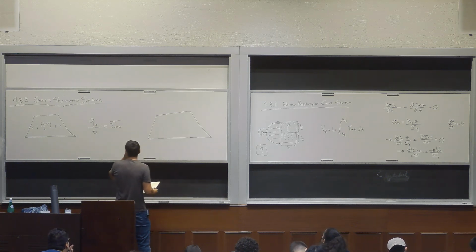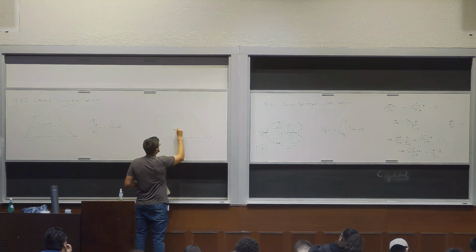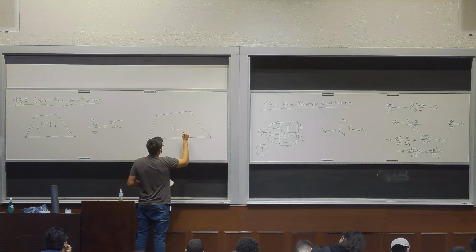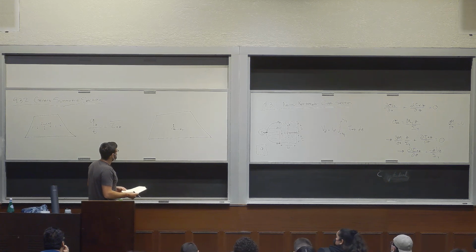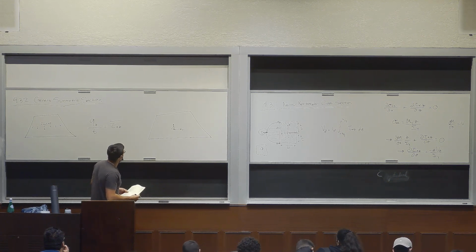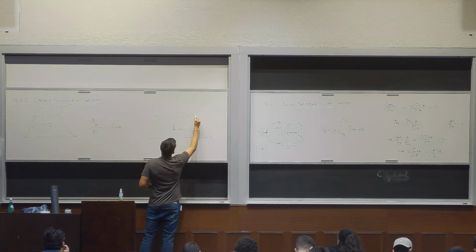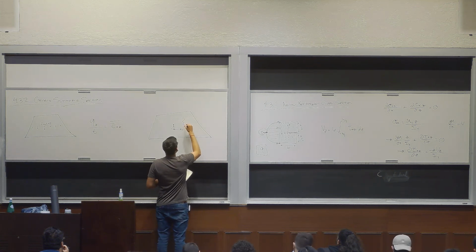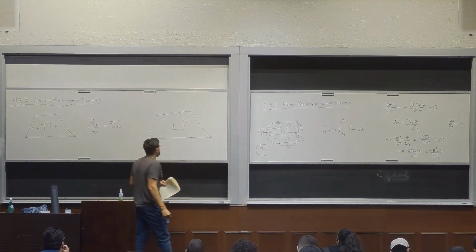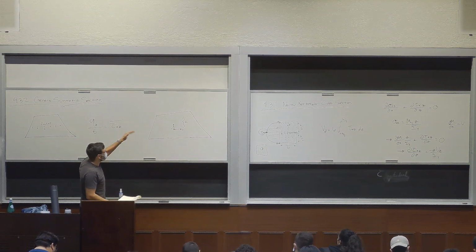The way you solve these problems is that you find the centroid. We've gotten pretty good at doing that at this point. Define your axes, right? This is the y, z plane. And let's say that we're trying to find the shear stress at this position z. Right, so this is z. So we'll call this distance here z1. Okay? The goal here is to find tau xz at z1.